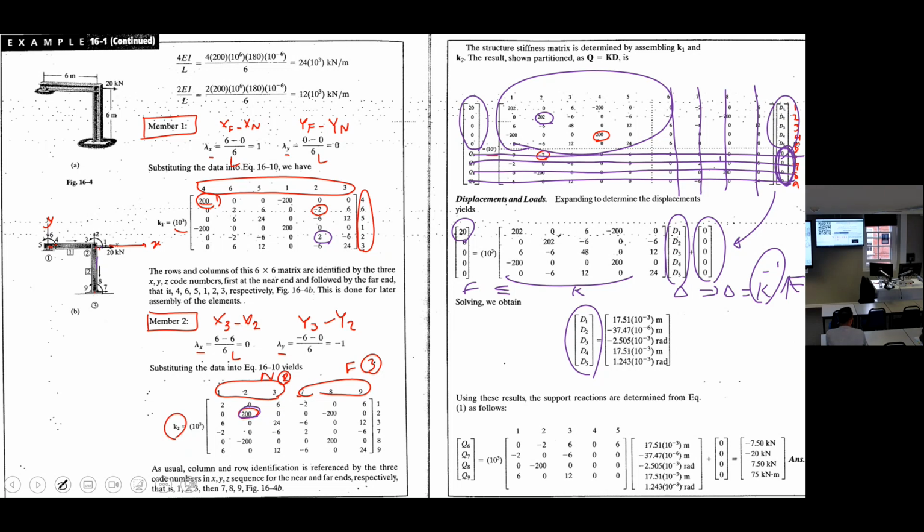In this stage, your structure is solved. You know the unknown deformations. Somehow it's over, finished. However, you might need to go for support reactions or internal forces, but every further unknown can be calculated based on these deformations. When you know your deformations in your structure, you know whatever you further need. Right? Questions until here?